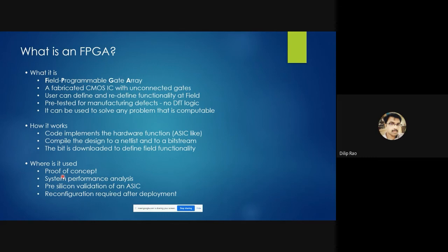There are several parameters that come with that. You need to support the expected bit rate and the necessary resolution of the video clip. Plus, you need to make sure that no pixel glitches are seen by the end user, which means there should be sufficient data streaming all the time. There should not be any back pressure at any point in the data path.